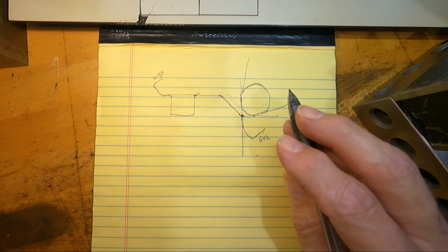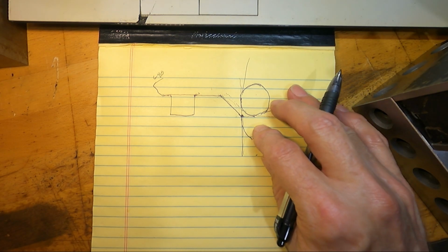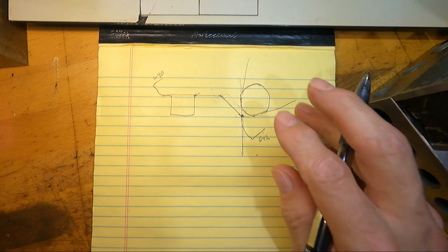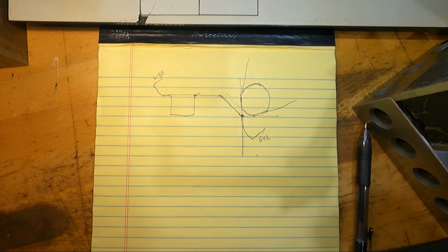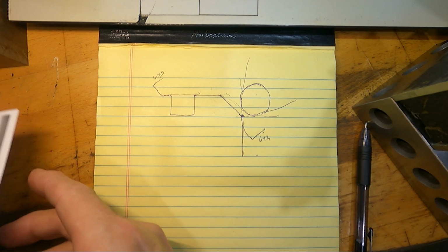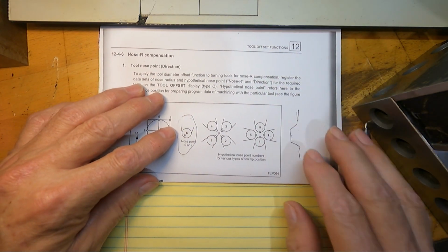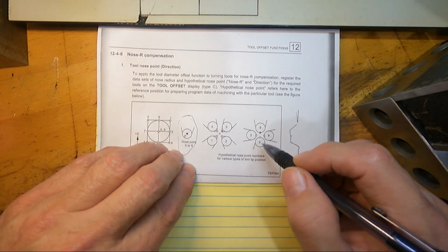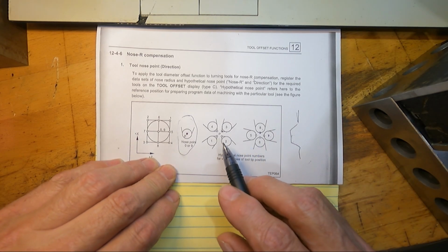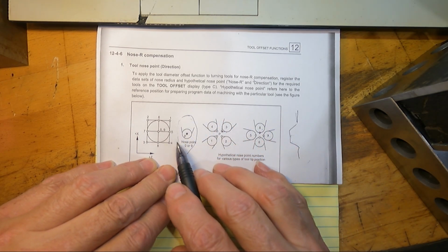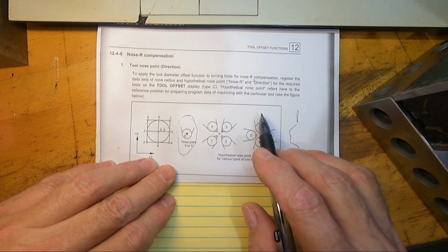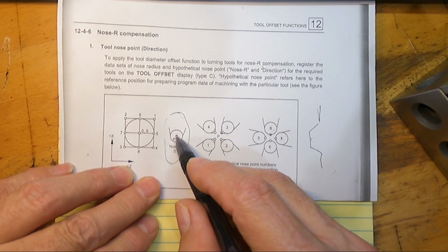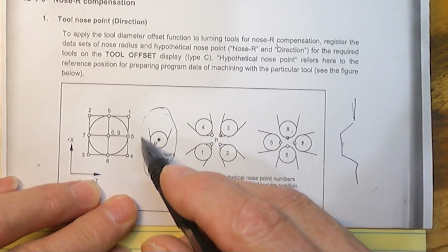So that kind of explains a little bit of why we used to use tip comp on a lathe. But it acts differently because of the way you touch the tools off on a lathe. So when you see a lathe manual, if you look in the programming manual, it probably would have this. You'll see this diagram, and it shows these directions of touching a tool off. Now you can touch a tool off in the center, just like this one shows here that are circled.